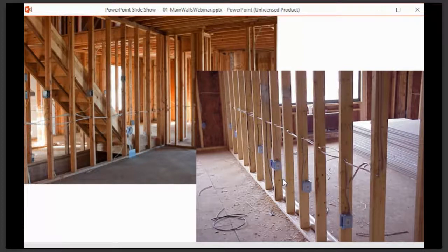So they have to work around each other. That's why, as we get on into the course, we'll talk about scheduling and how you coordinate the different people. This is also what we call first fix and second fix. Your electrical contractor will need to be there, first of all, for a first fix. And the first fix is literally just putting in the electrics, okay? Just putting in the wires, putting everything in place where it needs to be.